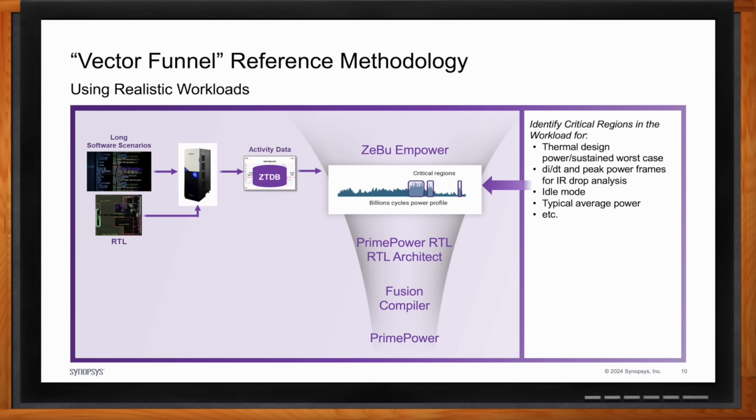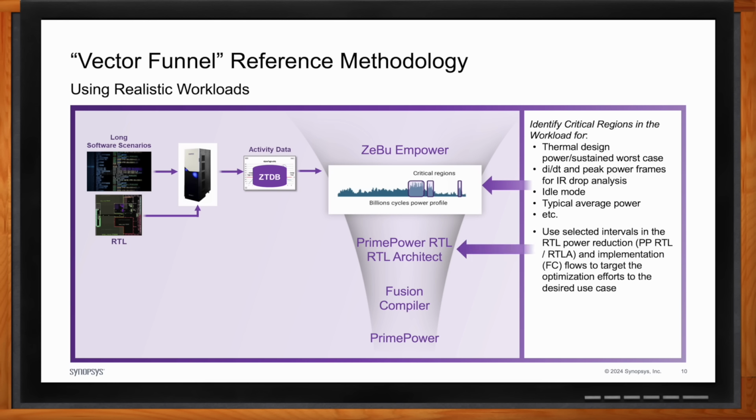And the RTL design flow will then take that activity, and other Synopsys solutions like PrimePower RTL Architect will use that information and target the optimization efforts for that specific portion of the activity. So with PrimePower RTL Architect, it's an RTL design phase. The tools will give you suggestions about rewriting the RTL. They're not going to output RTL for you, but they will give you suggestions about improving the RTL for power: improving clock gating efficiency, looking at the memory subsystem operation, and seeing if you have any redundant memory cycles, redundant reads, redundant writes, and so on.